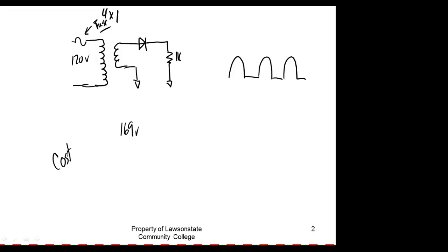Yeah, but that's not the average voltage. So what you did is you took this right here and converted it to VP. And you came up and got what, Courtney? That's 169 volts right there. That's not on the other side of that transformer, right? That transformer is a step down transformer. So right off the bat, see what you did wrong? You just stopped by converting VP.